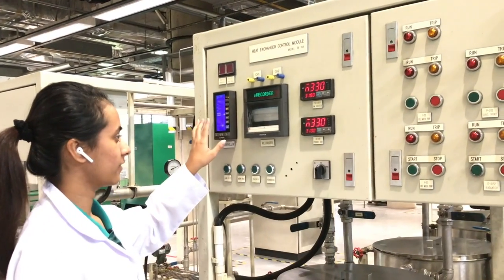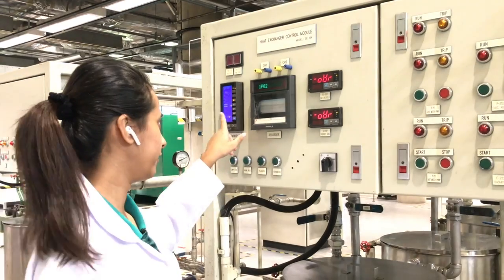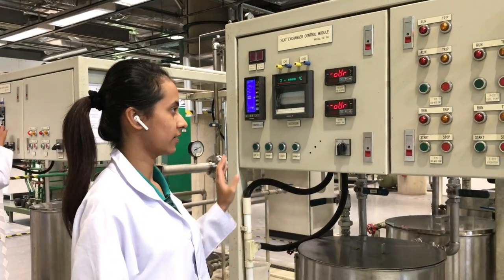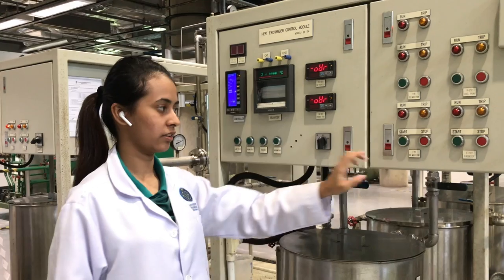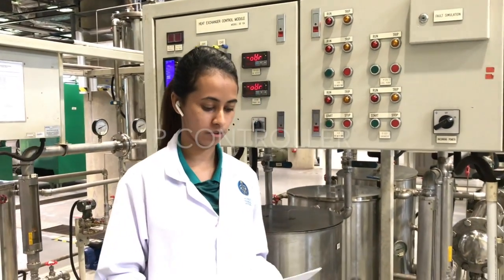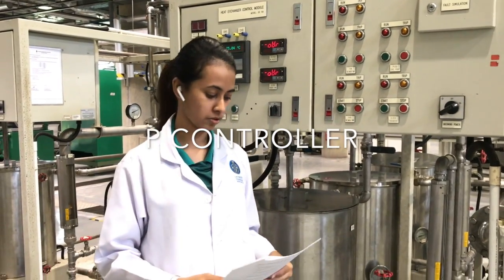and we can set the temperature for the hot water, which is at 65 degrees Celsius. Once the temperature has reached 65 degrees Celsius, we can switch on the hot water pump and the cold water pump. And after that, we can proceed with the experiment. For the first part of the experiment, which is the controlling using the P proportional only heat exchanger control.